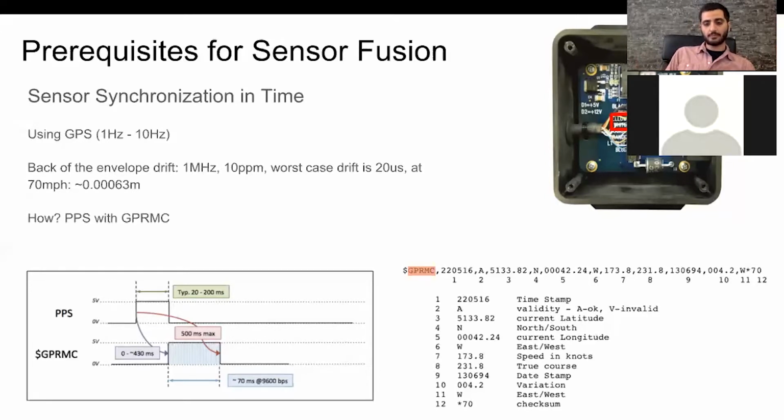So we're looking at the top right of the slide at a LiDAR interface unit. This is a unit that usually comes with certain Velodyne models, and we've highlighted a couple of signals. So of course we have power and ground and all the Ethernet signals, but in particular here we're interested in the two signals that say GPS pulse and GPS receive. As you might have guessed, the pulse is the signal which is responsible for getting that pulse per second, once a second, and then the GPS receive is responsible for getting a sentence over serial, essentially, that is telling it this is what time it is.